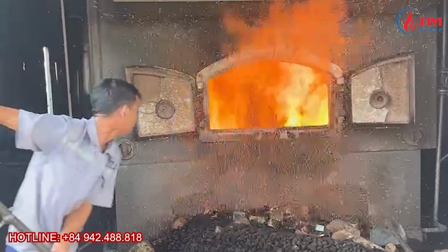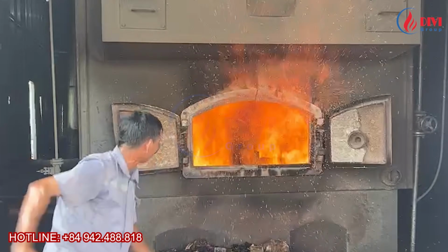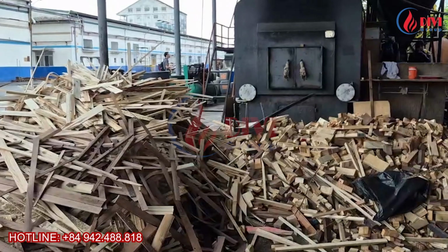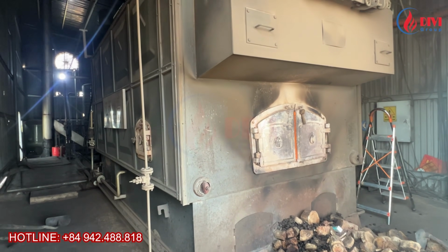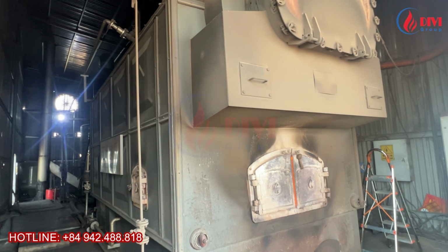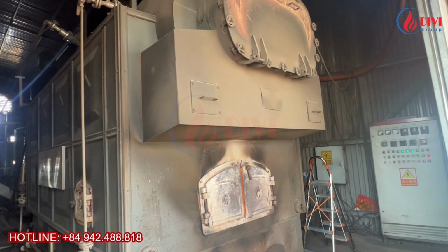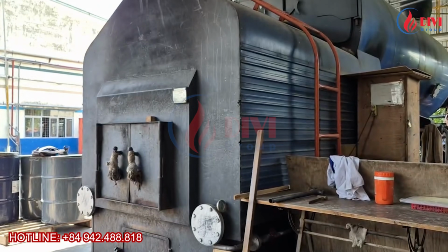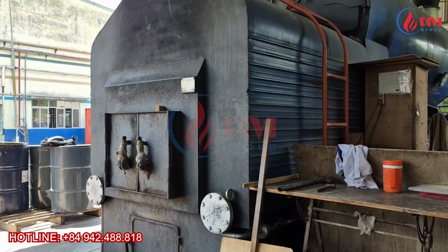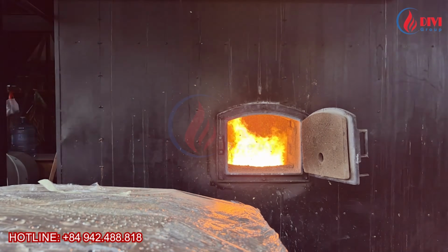However, in manually fired boilers, maintaining these conditions consistently is almost impossible. Since fuel feeding depends on human operation, there will inevitably be periods of overfeeding and underfeeding. As for combustion intensity, operators have very limited control because it depends largely on the furnace design. If the furnace design is inadequate, there is little that can be done other than using drier fuels with higher calorific value. However, this usually comes at a higher fuel cost.